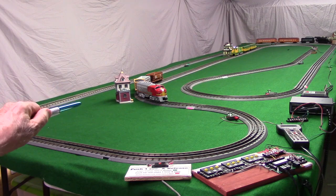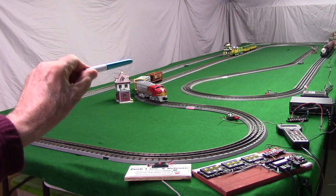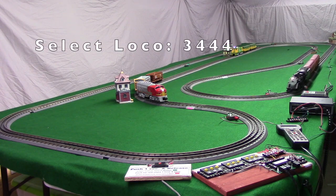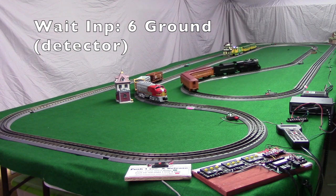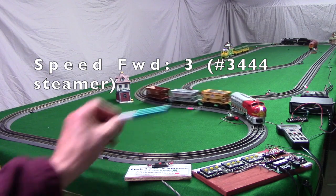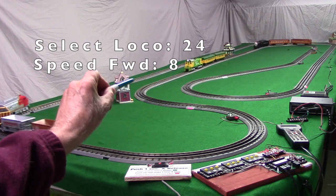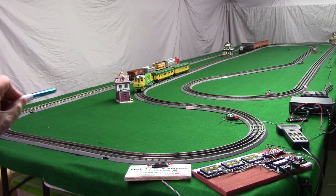We'll actually say select loco 24, speed forward 0, select loco 779, speed forward 0. That gets those 2 locos stopped in the yard. Now the steam engine is already selected, so when that crosses in front of the detector, or actually when the first car activates the detector, we say speed forward 3. We say select loco 24, speed forward 8, select loco 779, speed forward 4. Now we're executing a 14-second time delay.